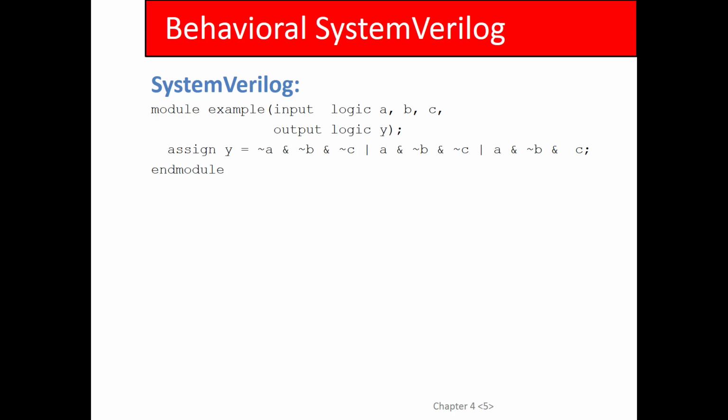No, it does have scope. The scope here is that Y is defined within this module as the output. If I instantiate that module somewhere else and I connect that Y output to another wire in another level of the hierarchy, it's the same signal, even though it may have different names depending on where you are in the hierarchy. But you can still only have one thing setting it in each module, right? But it's still accessible by other modules, so you can read it by as many things as you want.